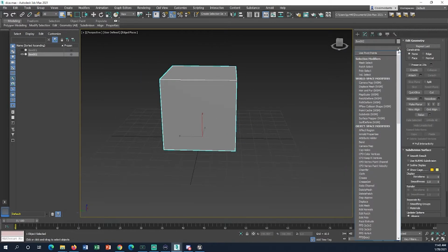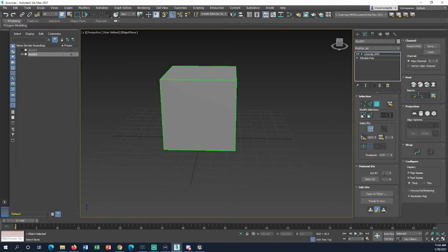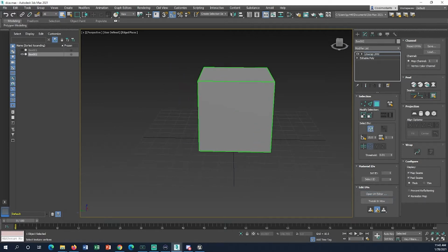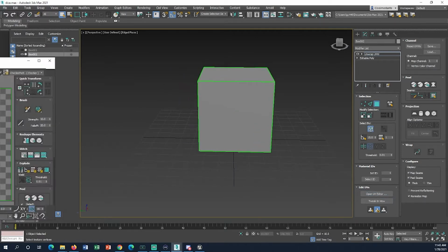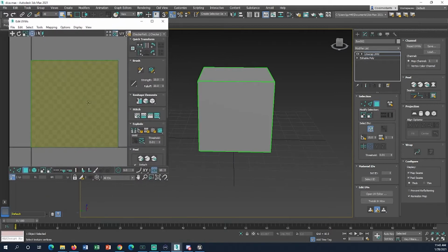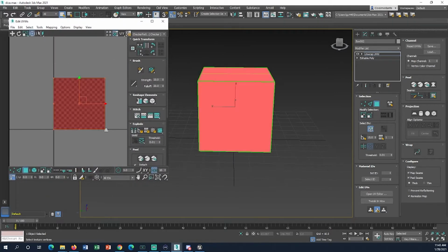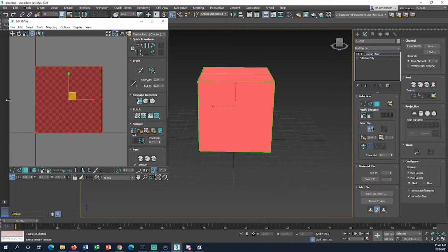Alright, first things first, I'm going to go over here and go to the UV unwrap section. I know there's a lot of information on this page, but it's way simpler than you think. Alrighty, so when you open that up, you get a window that looks like this. And this square with the checkered patterns, this is where basically all of your texture information will be. It could be 1024, 2048, 4K, any sort of resolution. But this is where all the pixels are going to live for the texturing for our model.